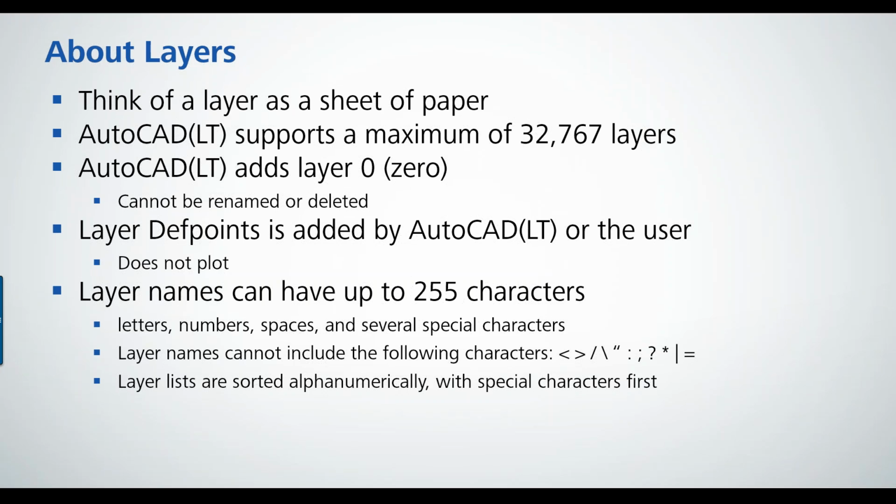Voker did a great webinar on XREFs and XREF management. If you haven't seen that one, I would recommend taking a look at it. Although it allows that many layers, you certainly would notice some significant performance issues. I think it's set to that so that you really won't ever run up against any problems with not being able to add the layers you need, but performance-wise, you would never want to approach that number.